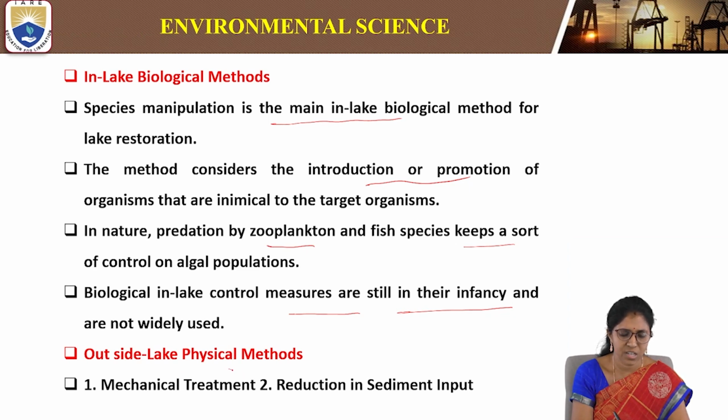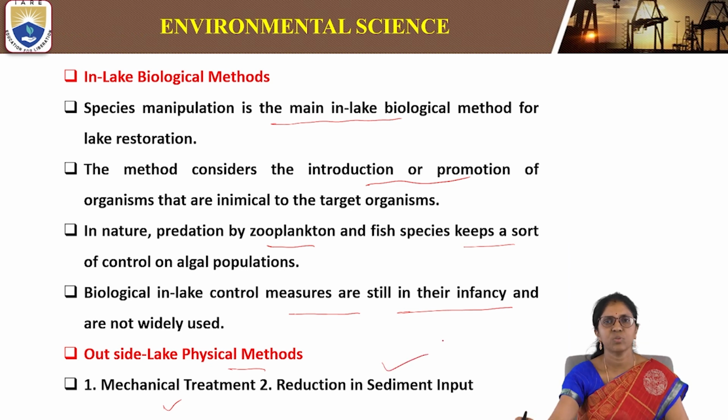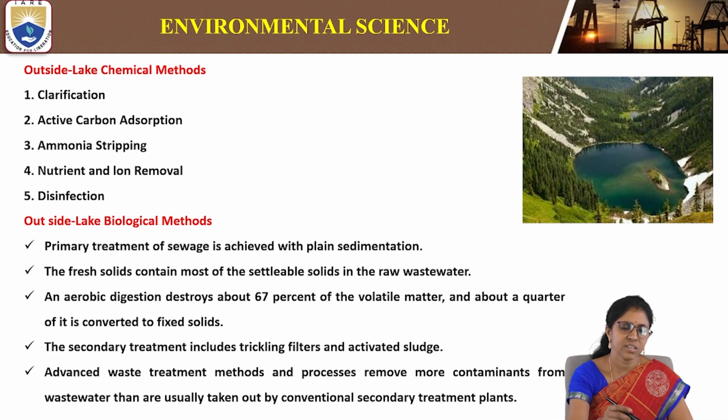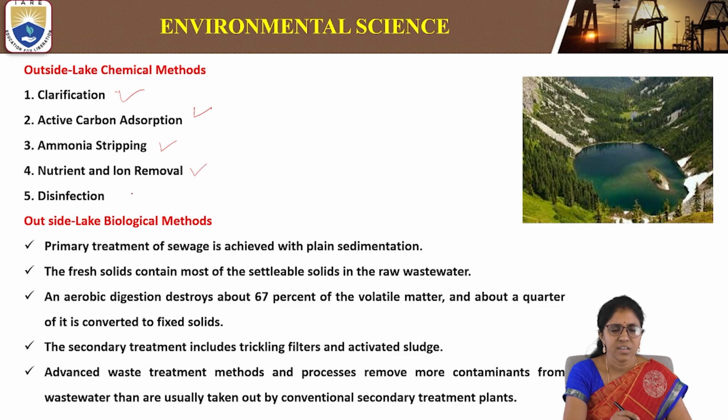Outside-lake physical methods include mechanical treatment as well as reduction in sediment input. Outside-lake chemical methods include clarification, activated carbon adsorption, ammonia stripping, nutrient and ion removal, and the disinfection process. These are outside-lake chemical methods. By using the disinfection method, we can kill all the microorganisms which are present in water. So this is the disinfection process.